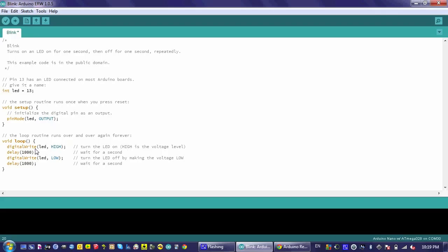If you wanted to make something that could dim or be moderately bright, you would use an analog write. Here we just want to make the light come on, so we're using a digital write. I'm telling it which pin I want to turn on, and I'm telling it that I want it to turn on. The HIGH means on, or 5 volts, or true, or I'm setting it up so that it provides